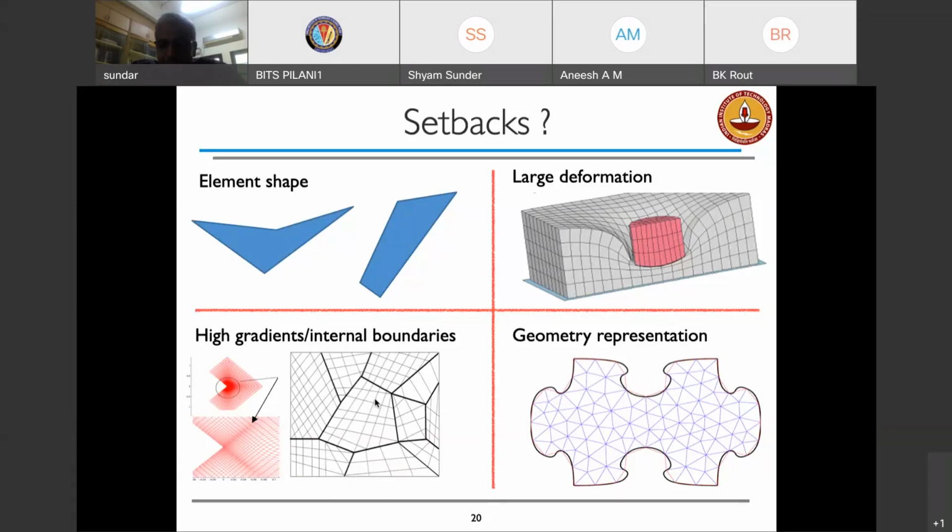if you use a numerical technique to solve. So the last of the difficulties, there are other challenges, but the last of the difficulties that we want to highlight here is a geometric representation error. Remember, we had a picture of a circle. We divided the circle into small triangles. And we know that by dividing into triangles, we are only approximating the circumference of the circle, because the triangle cannot exactly represent the curvature of the circle.